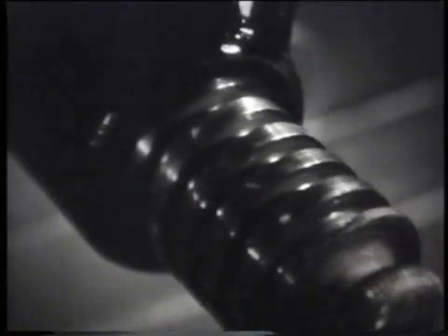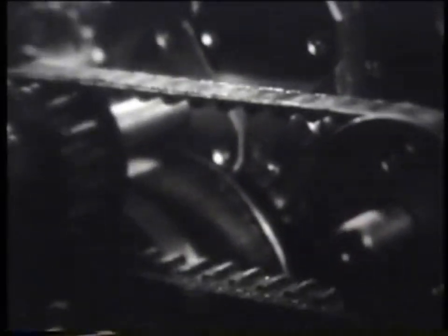In all these mechanisms, the links are solid bodies, they retain their shape in the process of movement. In belt mechanisms, a flexible link is used, a belt. This link bends during operation. Different types of belts allow you to get a variety of mechanisms. Mechanisms with flexible links also include cable ones. A flexible link in them is a rope, metal or made of synthetic materials. The flexible link in the chain mechanism is a sleeve roller chain.